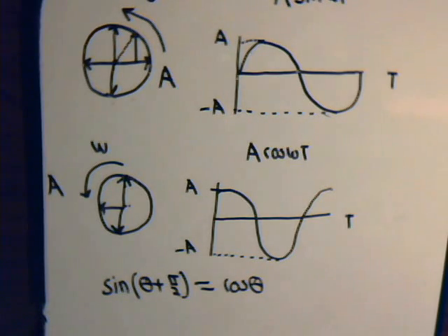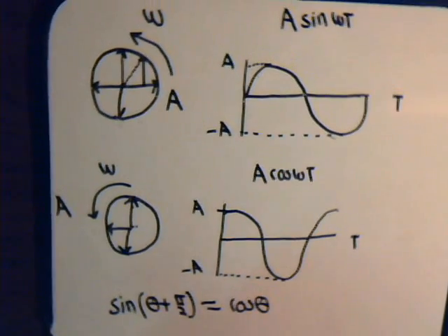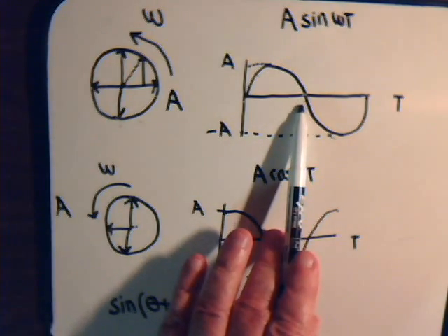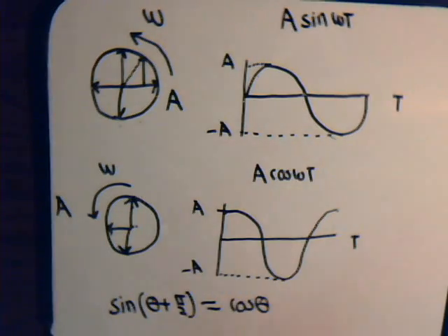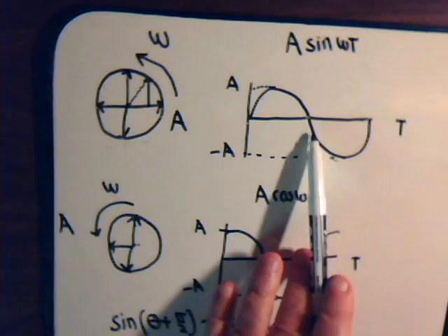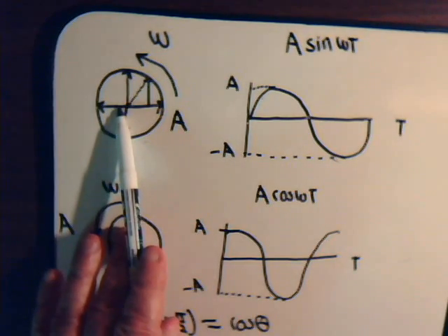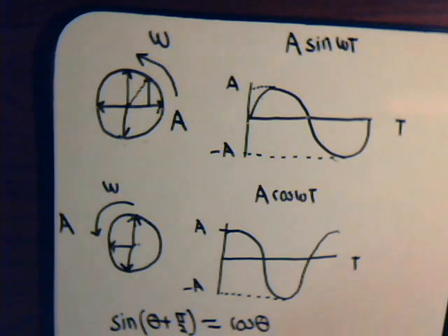So the point is that we can represent information with the phasor diagram, or that same information here as a sinusoidal wave. And here, this is usually called the time domain, and this is called the frequency domain. Now, in the frequency domain, or the phasor domain, usually the relevant information is the magnitude of the phasor, or the circle radius vector, and the phase angle.